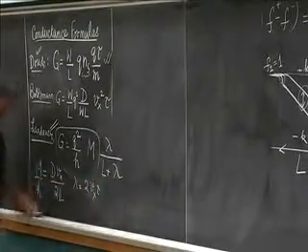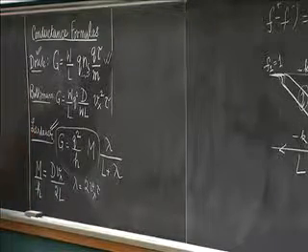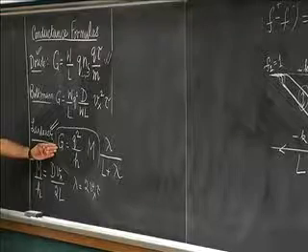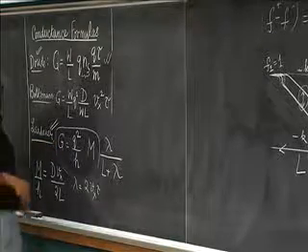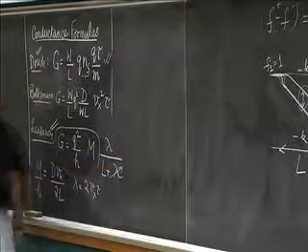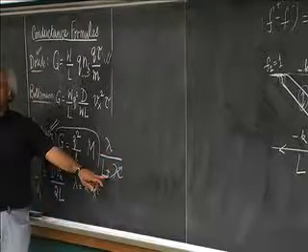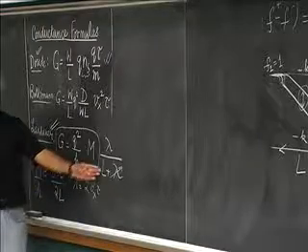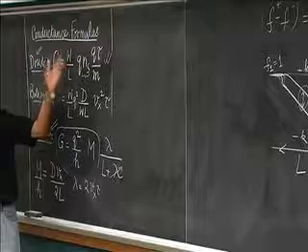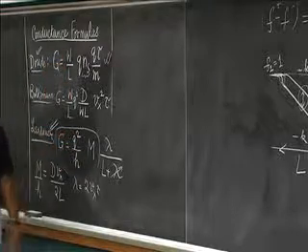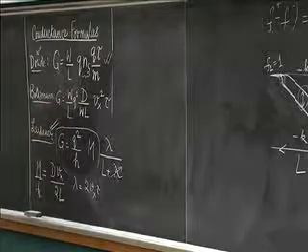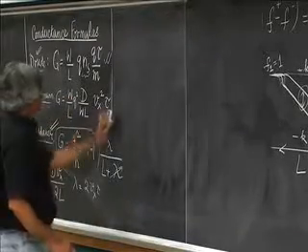So I'd say that from the Landauer viewpoint, if you proceeded, this is the expression you'd come up with. See? And then if you apply it to a long device, you'd say, okay, let me drop the lambda here, drop the mean free path from the denominator, and you have a conductance that goes down as length, just as it should from Ohm's law and all that. And you'd have something looking just like that. See? Now, how do you connect these two things? Well, you can kind of see how it works.